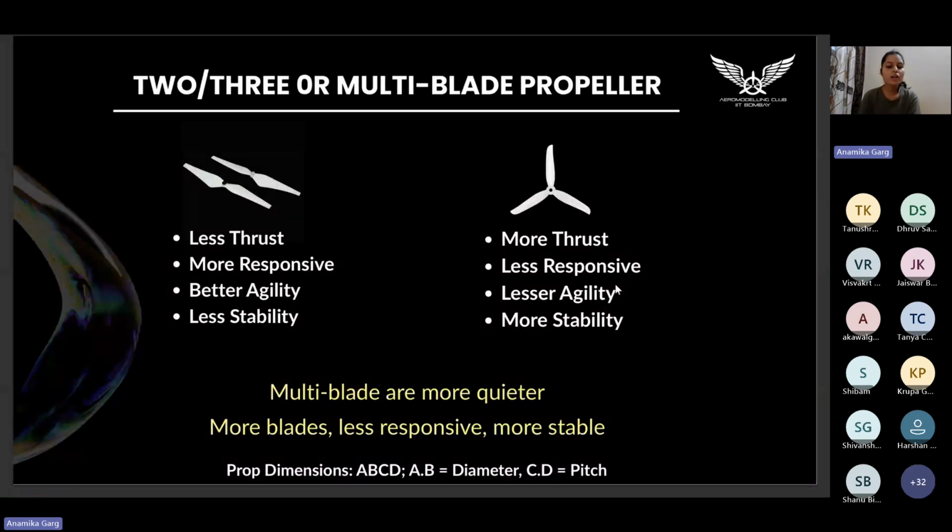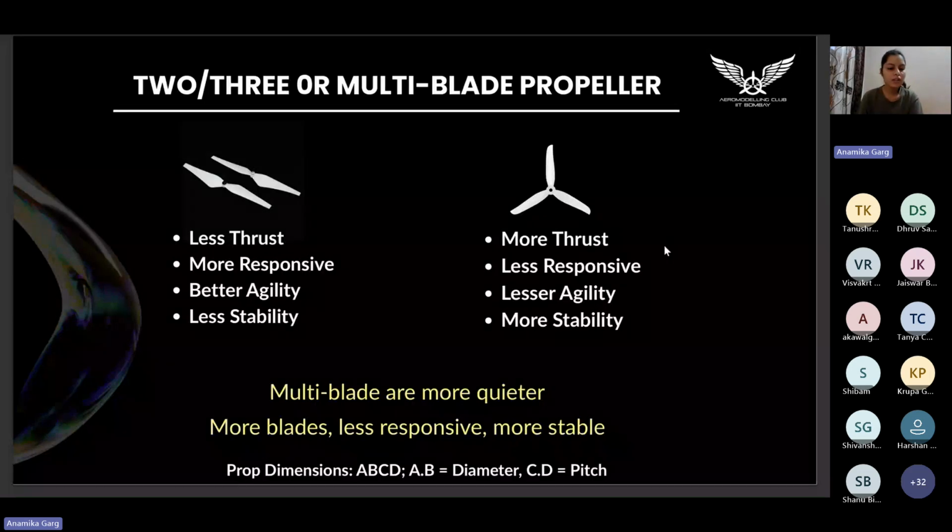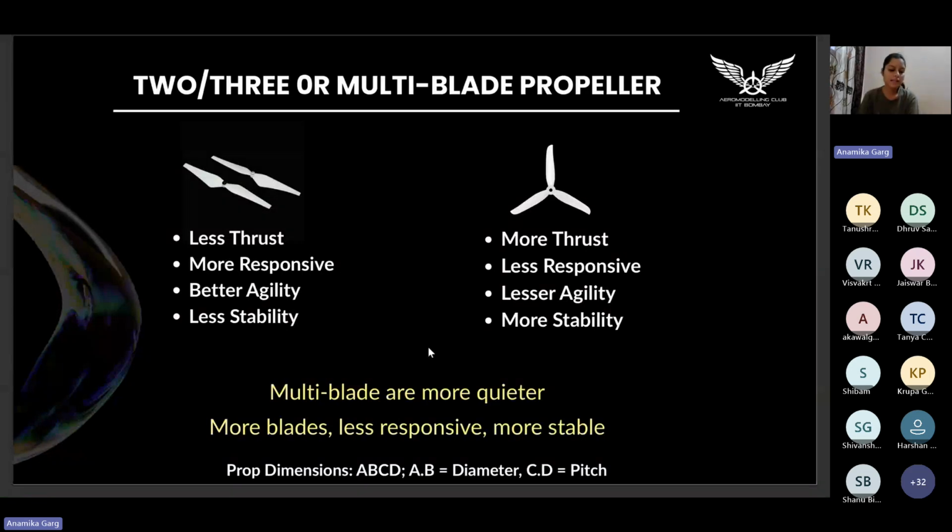According to your mission, whatever your problem statement is, you will choose whatever blades you want in your propeller. When you go for a multi-blade propeller, it also gets quiet. So if that is in your problem statement, you might want to consider multi-blade propellers.